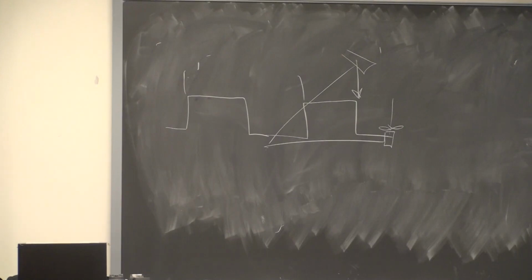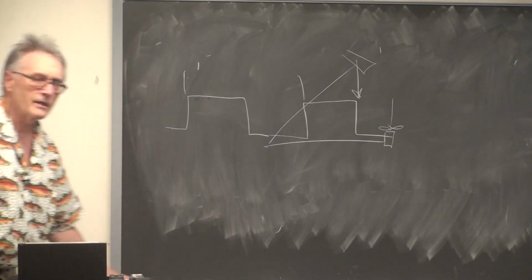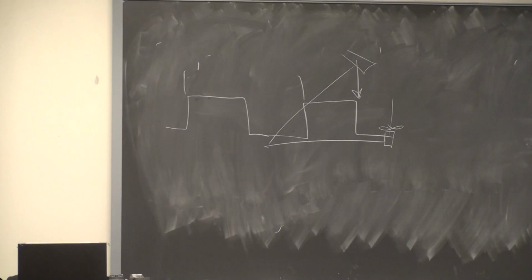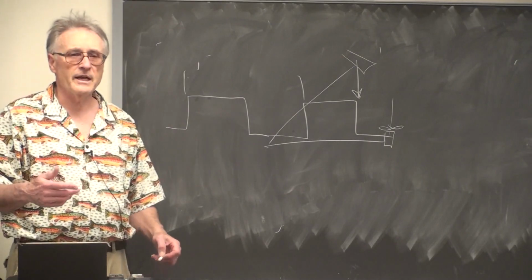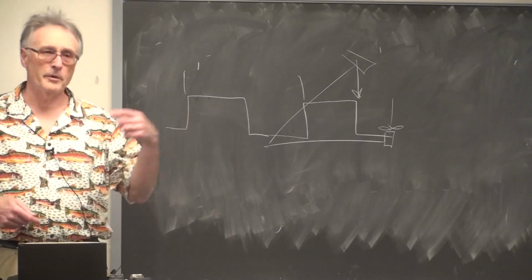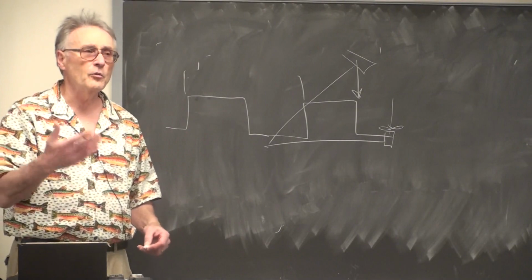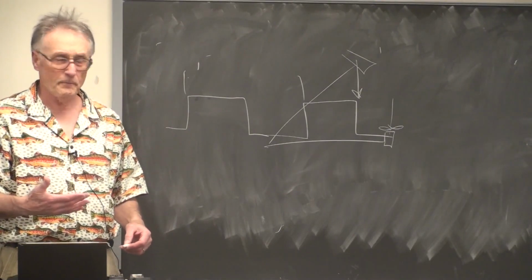So another way to do it is you write in your scheduler, you're going through these threads very, very quickly. Let's say you comment out everything in every thread, so that the scheduler is just sitting there saying, are you ready to execute? Nope. Are you ready to execute? Nope. Are you ready to execute? It's going through that loop millions of times a second.